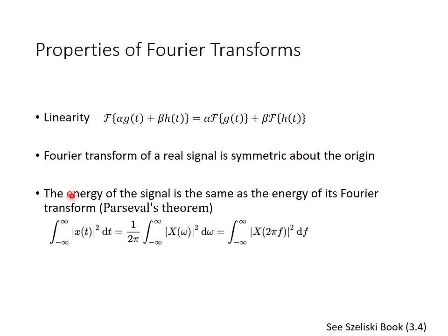Again, remember, we transform an image to its frequency domain, and we use the inverse Fourier transform to reconstruct the image, and there is no data loss. So it is the energy preserving property. If we convert a real image to its Fourier domain and back, then the results are still the same.